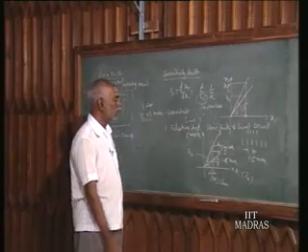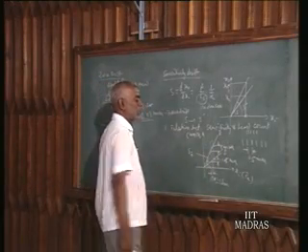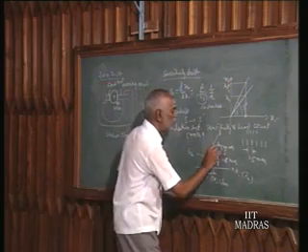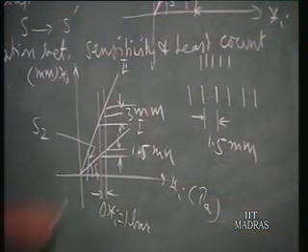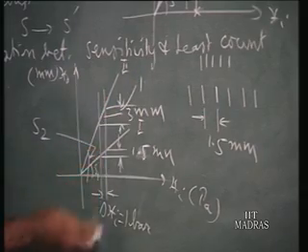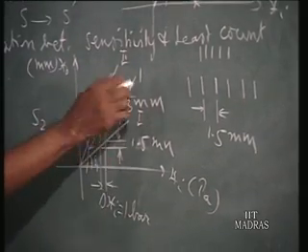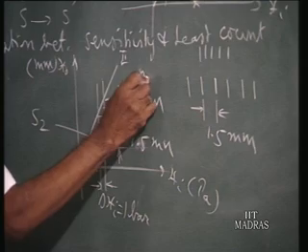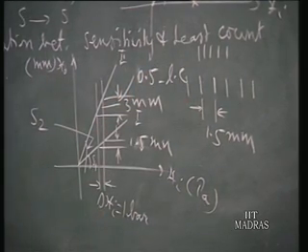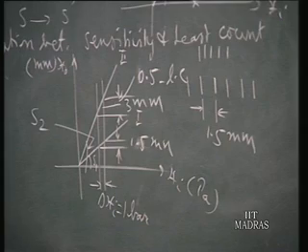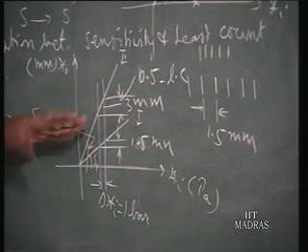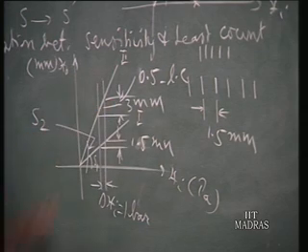So, in this case, since for 1 bar it has given 3 mm, I can have 2 graduations of 1.5 mm. So, the least count here can be 0.5 bar. For 1 bar it has moved 3 mm and it can be divided into 2. So, 0.5 bar is the least count. For the first instrument, the least count can be 0.5 bar, because for 0.5 bar itself I got 1.5 mm. Less than that means the graduation distance will reduce, and I cannot do that.